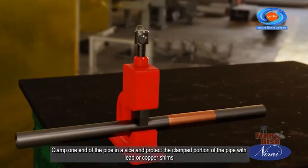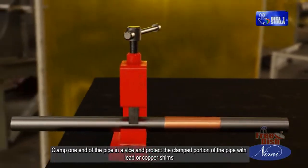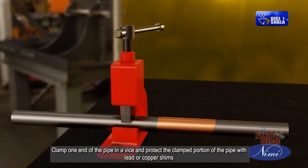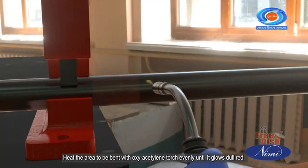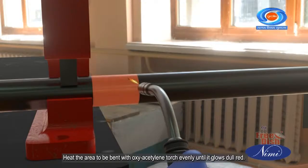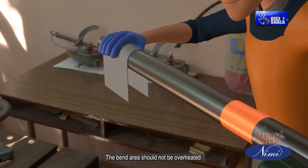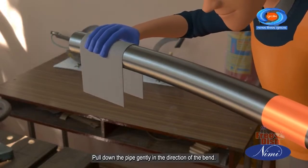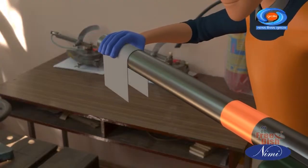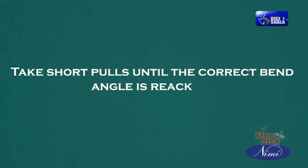Clamp one end of the pipe in a vise and protect the clamped portion of the pipe with lead or copper shims. Heat the area to be bent with an oxyacetylene torch evenly until it glows dull red. The bent area should not be overheated. Pull down the pipe gently in the direction of the bend. Take short pulls until the correct bend angle is reached.